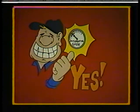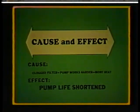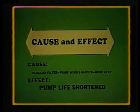The differential pressure gauge used in either a vacuum or pressure system gives total information as to the airflow through the instrument. The pressures of the instrument inlet and outlet are compared, and if the airflow is restricted into or out of the instrument, the differential pressure will be noted. Since the main function of an air pump is to move air, anything that restricts this flow of air causes the pump to work harder, generating more heat. The restricted flow also deprives the pump of the cooling air it needs, thus shortening its service life.